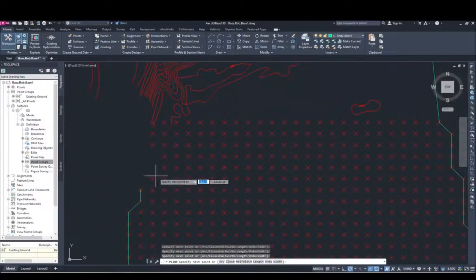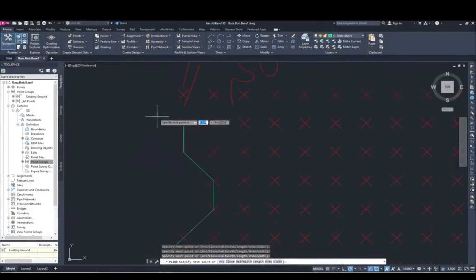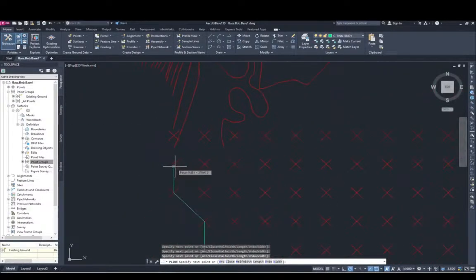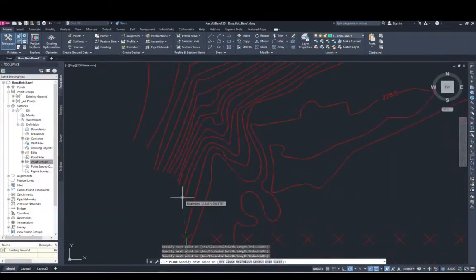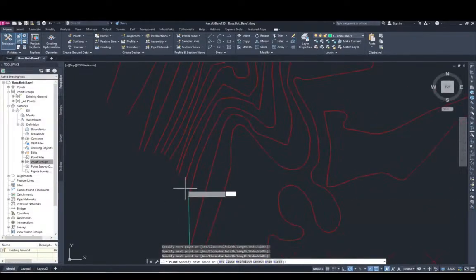We can do two 45s here. Okay, now we're getting to one of the points I want to make here. Over here, you can see the nodes and the endpoints, they kind of overlap here. So you want to kind of hit all of them. So we see here I'm at a node here. I'm going to hit this endpoint, then another node, and then another endpoint. And then we got a lot of little tight endpoints here. You can zoom in, make sure you grab all of these.